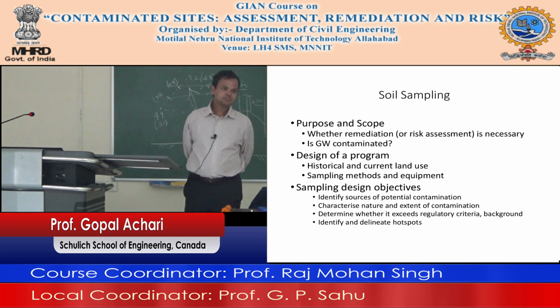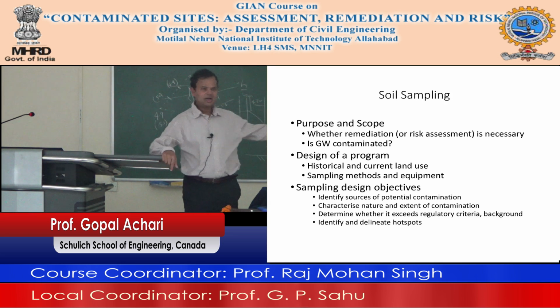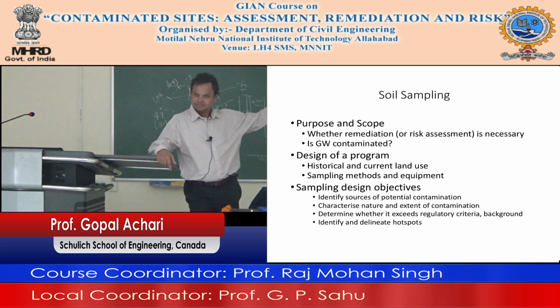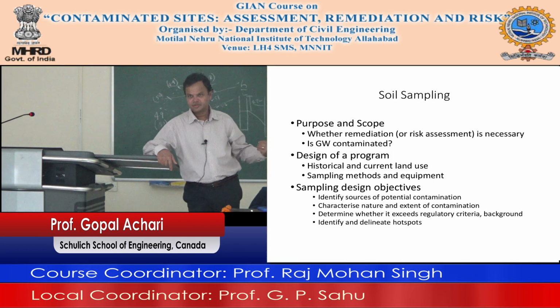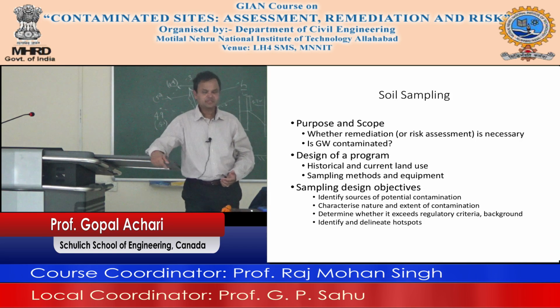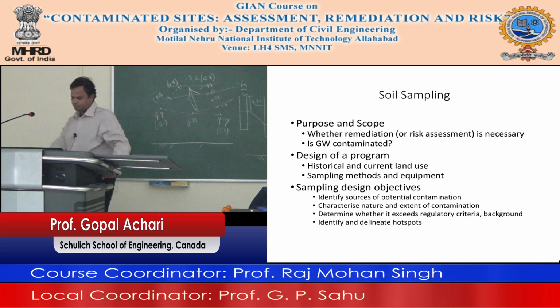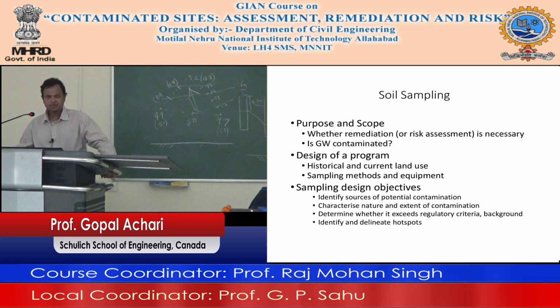The background is typically upwind from that site, maybe a kilometer upwind, where it's not carried from here downwind. You need that background information, because if the background concentration of that particular thing is high, then that will explain why you are finding high concentration and not necessarily activities.